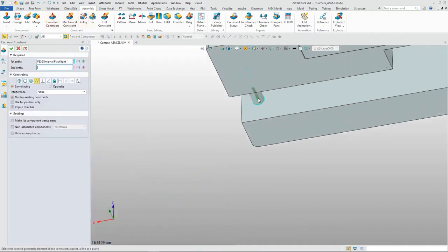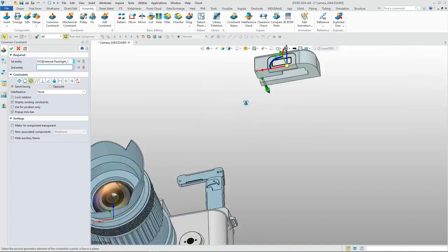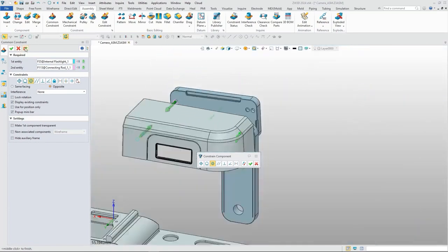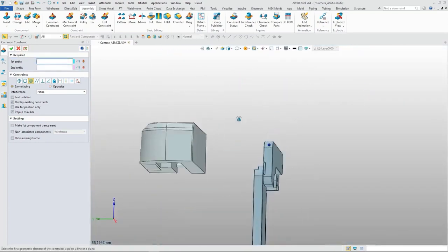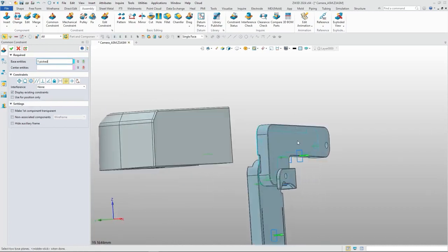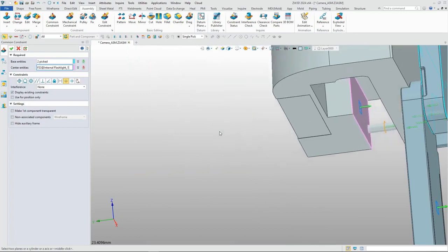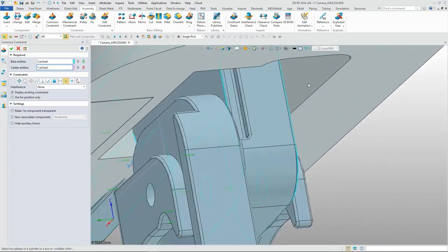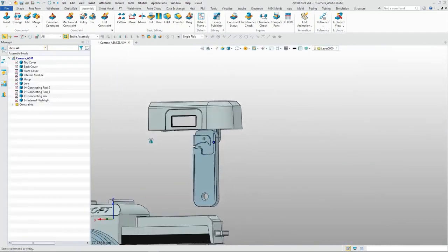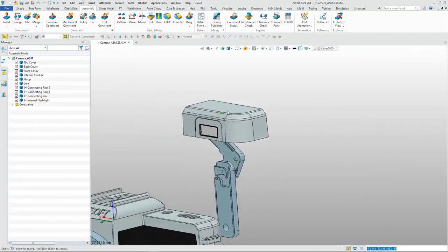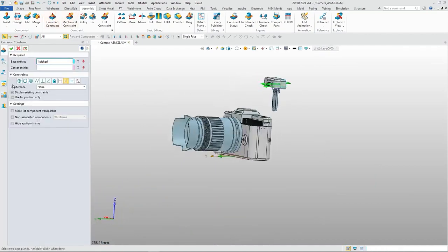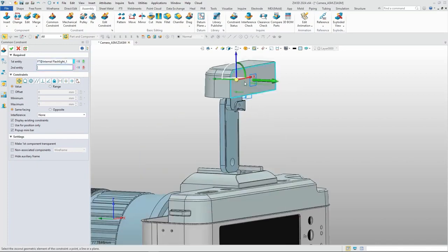Add the concentric constraints and middle constraints to mount the internal flashlight on the connection components. To make sure the flashlight and the connection components assembly is in the right position, we use the coincident constraints together with the offset range, and set the minimum and maximum offset values for it.